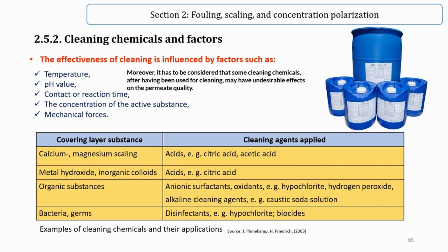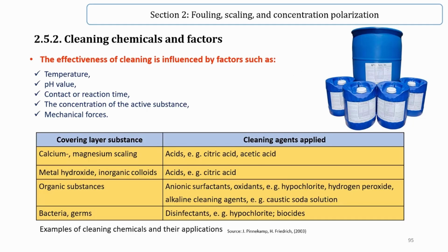Moreover, it has to be considered that some cleaning chemicals, after having been used for cleaning, may have undesirable effects on the permeate quality. After cleaning, these cleaning solutions have to be collected if necessary and disposed of separately.